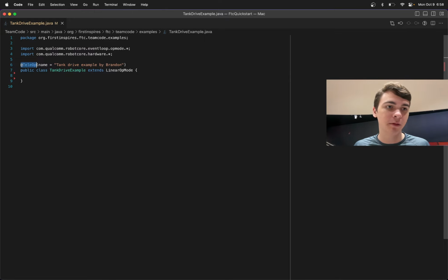The only thing we really need to worry about is that it has to be here for every TeleOp program. The other thing we need to do is give it a name. You don't need to do this. You can just leave this blank, and it will just give the class whatever name you name it here. But I like to be a little more specific. So this is tank drive example by Brandon.